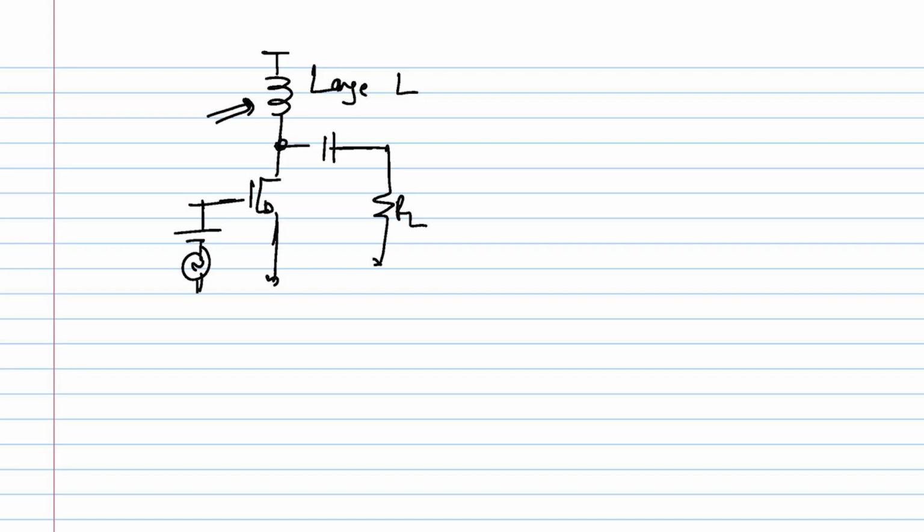Such an arrangement is often used, and I will show you a simplified version of it. Let's assume for the time being that the load is connected directly to the drain to make the points simpler, and let's further assume that this is biased. This is RL. What I am saying is, let's assume that the transistor is biased just above the threshold voltage.